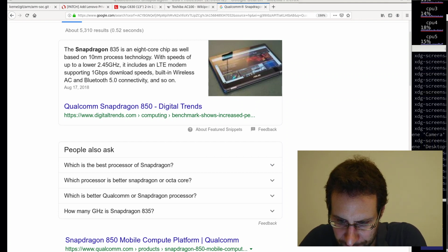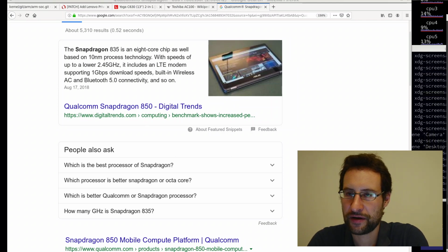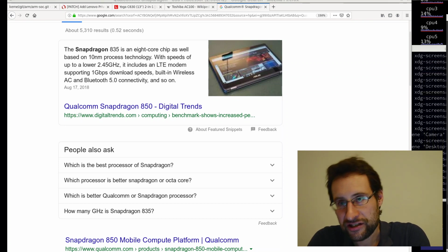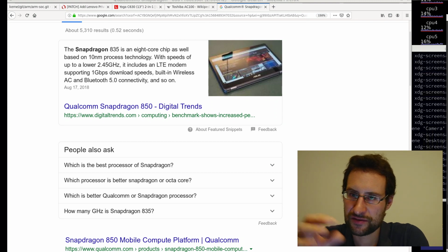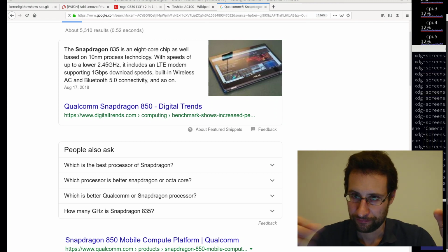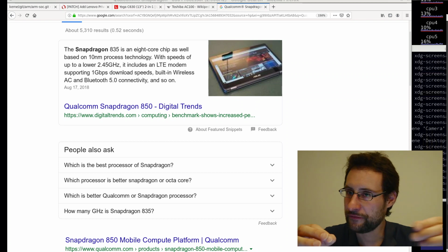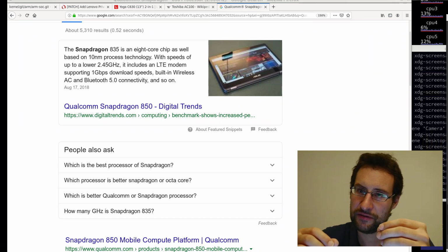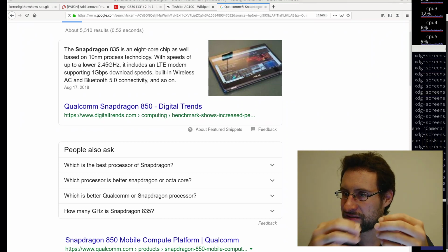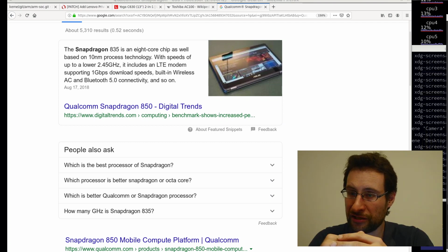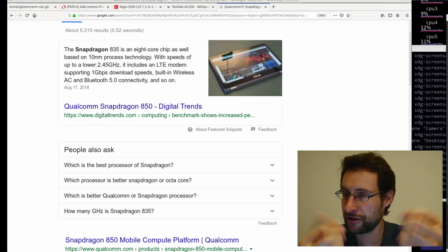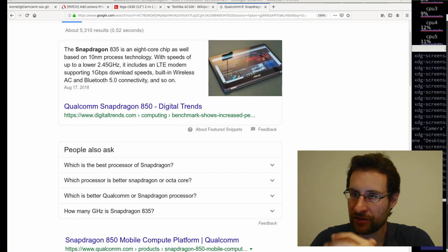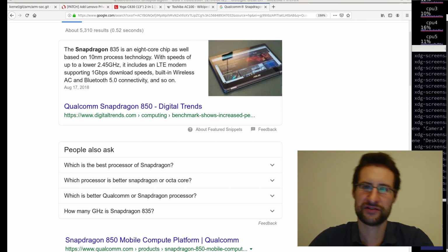So yeah, but otherwise, if you have your Raspberry Pi, micro HDMI is for me not the biggest showstopper, but the only problem is the smaller the stuff is. Sorry, I would worry a little bit that if you plug it in and out, that you shear it off of the PCB, or either the connector wears off with plugging it in and out again, or you really need to be really careful plugging it in and out again, not to shear the soldered SMD connector off of the PCB.